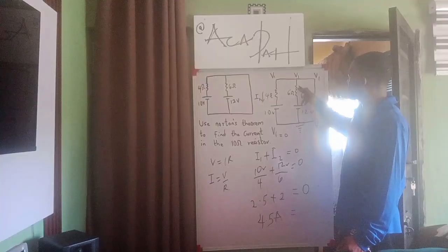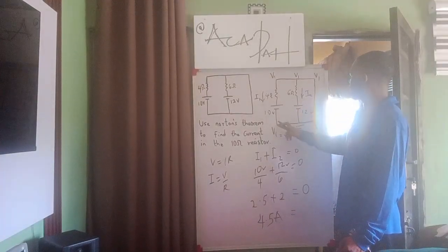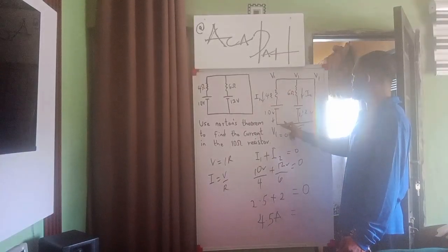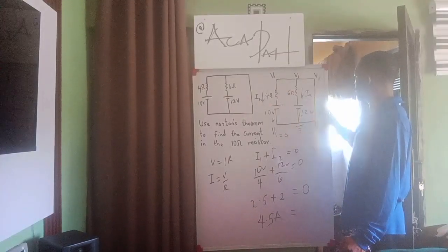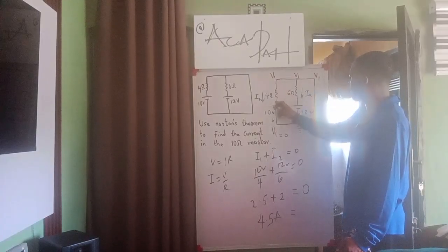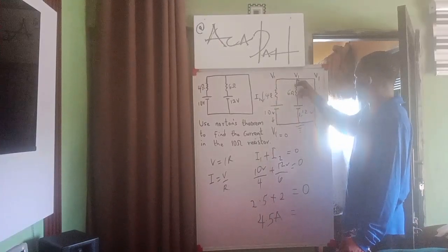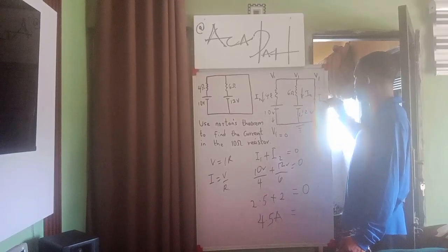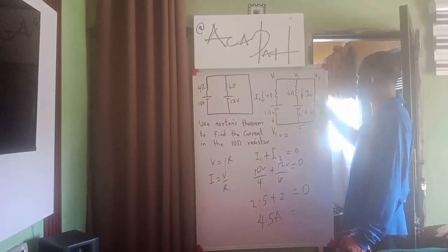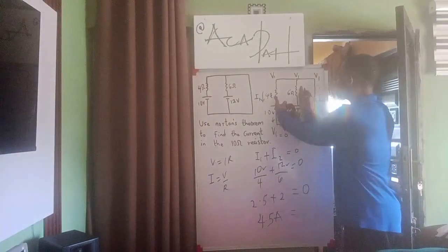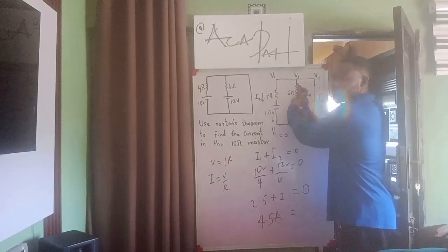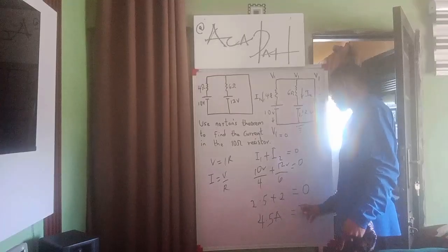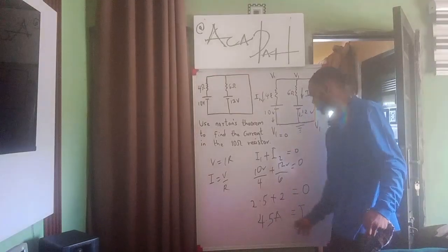Remember that since this is moving this way to the ground, it's leaving coming here, and that means everything here will be going this way and everything here will also be going this way. So that means that our IN, that 10 ohm resistor we removed, we short circuited, is going this way. The combination of these two currents, because this is the whole current inside this node, is just a node. The total current in this node is 4.5. That means it is equal to our IN.